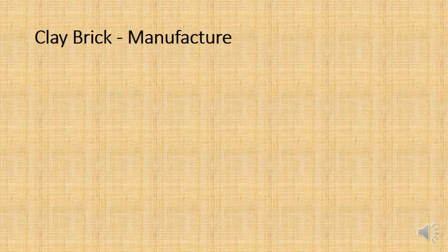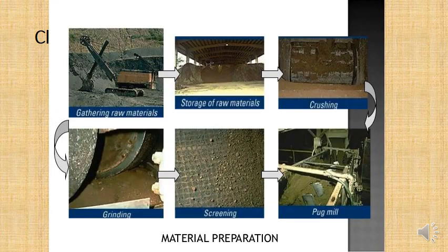So how do we manufacture clay bricks? Well, there's a video that I'm posting online, and I recommend you watch it. It's going to be on Moodle, and you can watch a clay brick being made. It's very exciting. But basically, you've got a bit of a process. First off, you're gathering the raw material. So you can see there in the top left-hand corner, they're actually collecting clay and probably a bit of shale there as well.